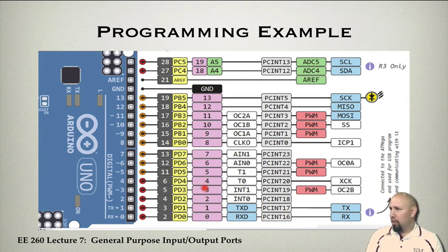These are 2 of the pins we want to use. The others are the pulse width modulation pins. We wanted to set those up as output pins, so those are pins 3, 5, and 6. Pins 2, 4, and 7 would be the other input pins. So we're going to set pin 2 as an input pin, pin 4 as an input pin, and pin 7 as an input pin. And then we're going to set pins 1, 3, 5, and 6 as output pins.